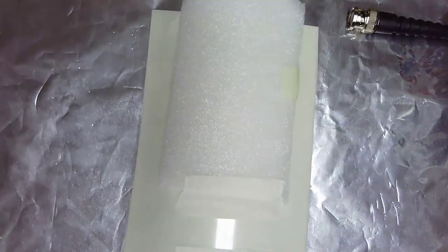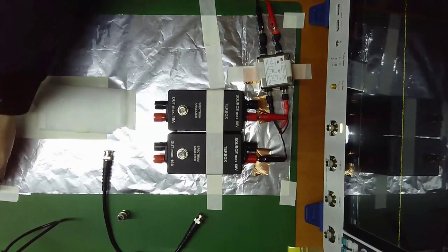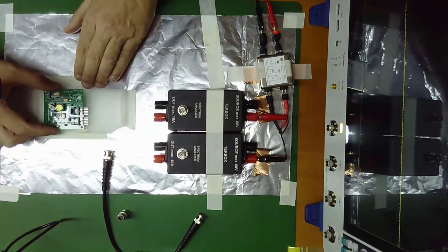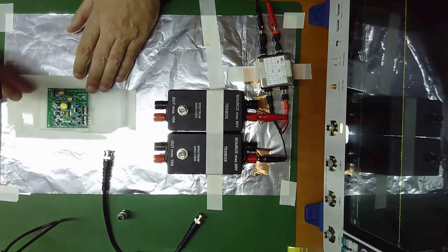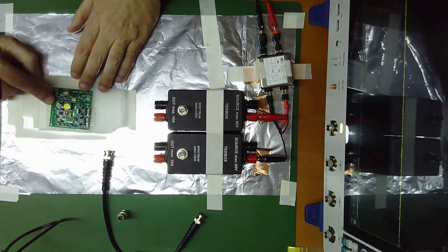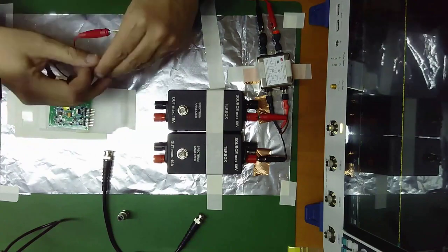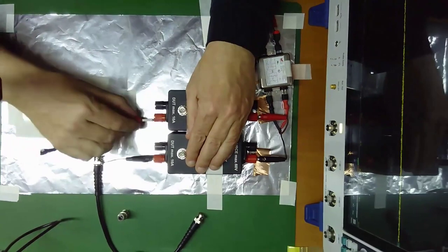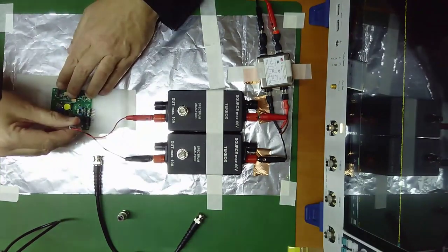So let's connect again here to see the details of the device under test. Okay. So if we are interested in measuring conducted emissions of the device, we will need to put our device on top of a dielectric material. The height of the dielectric material is usually explained in the regulations. We need to power our device. So I will be using this short cable, in this case for my demo.